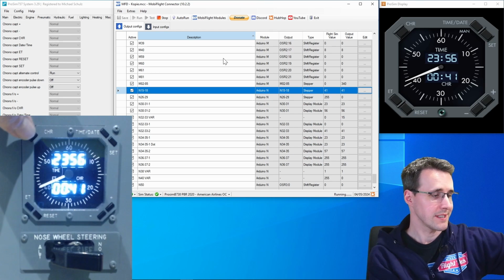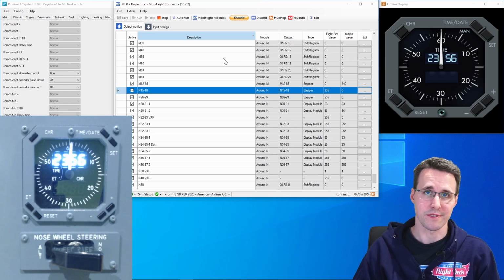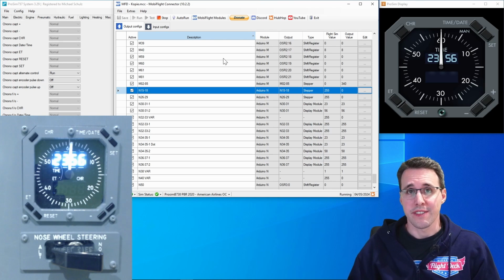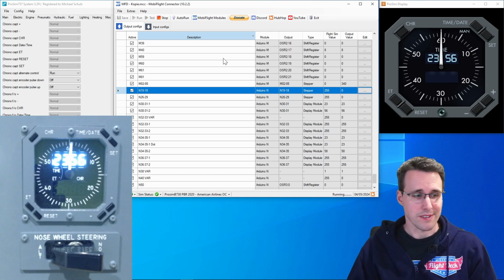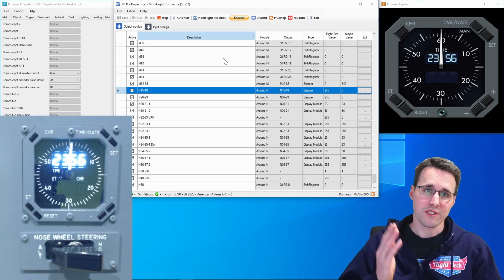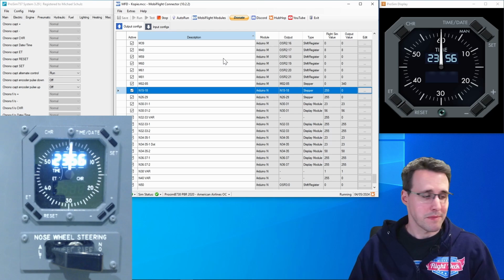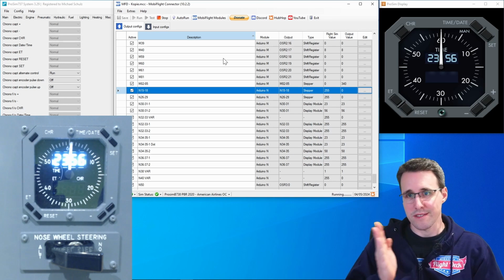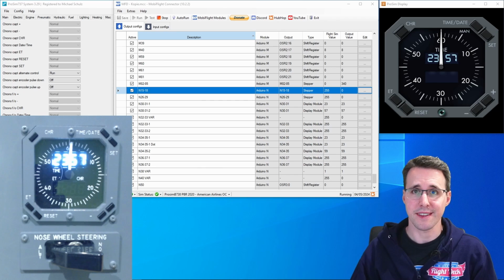And when I now reset it, it goes back to its 0 position. So I wouldn't have thought that this small checkbox has such a dramatic result here. I think in use cases where the stepper motor should stop for a longer time at a certain position, this might make sense. But in this case, where it has to start and stop so often, just let the stepper motor be powered.